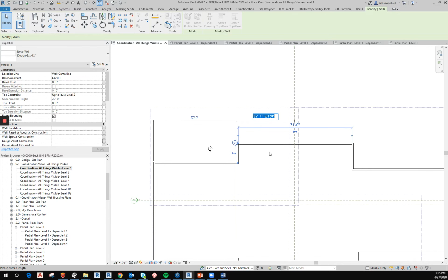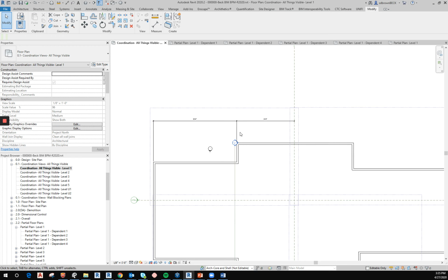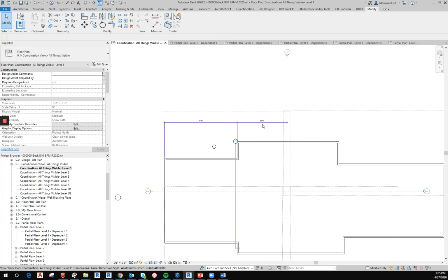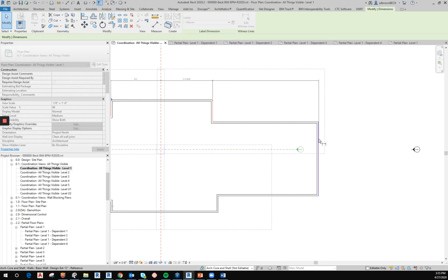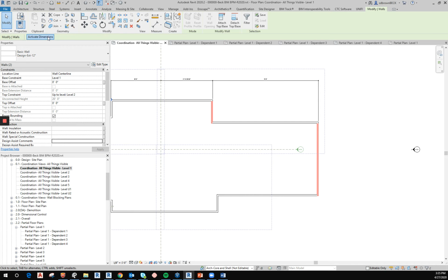So if I'm just sketching and I see that this is close but not very good, I will take those two and activate that and say, okay, let's make that 36. And then now this is a nice clean dimension from that origin point. And I would likewise go through and check the rest of my dimensions. And okay, I sketched that close to 37.